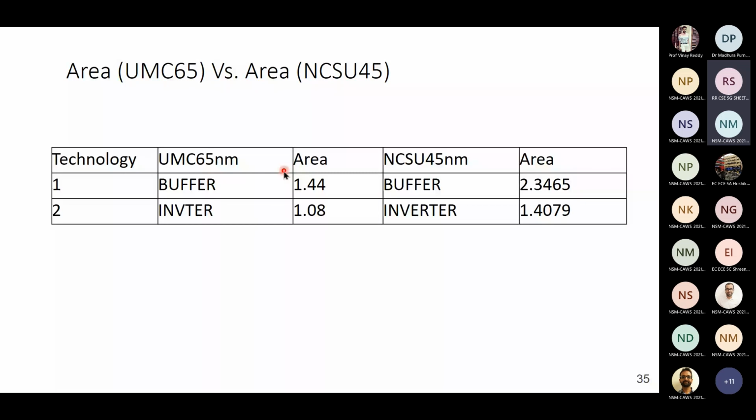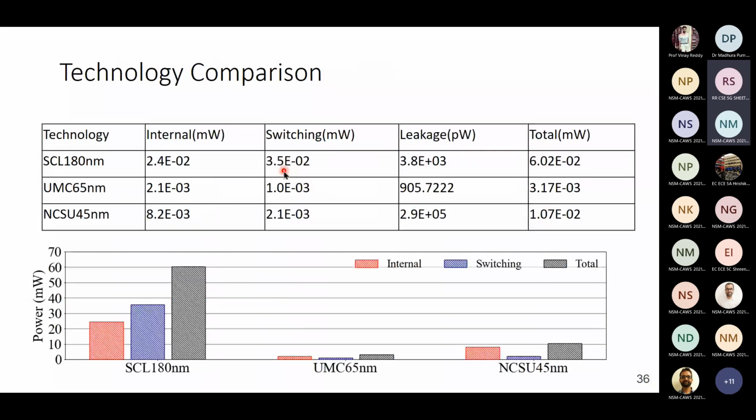Yes, and then we have also done the technology comparison for power. This is the same click controllers with multiple power components. As you can see, there is a significant amount of power that goes into the click controller. When I say significant, our job is to compare this with the clock tree power. That's the eventual goal. Currently, it's a study that's going on. Our goal is to minimize the click controller power so that we can benefit when we remove the clock tree.